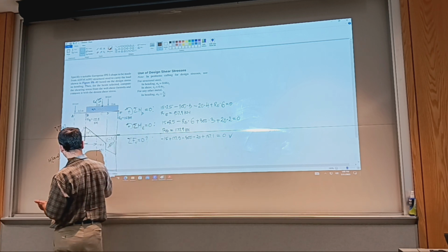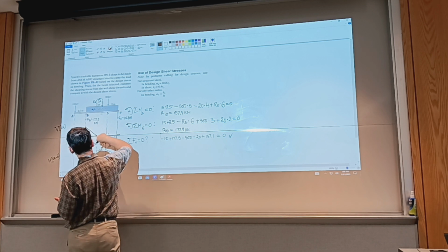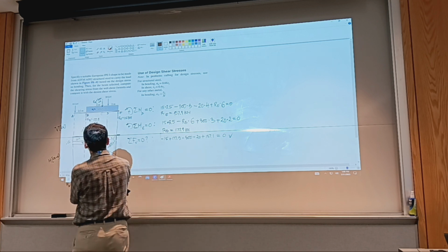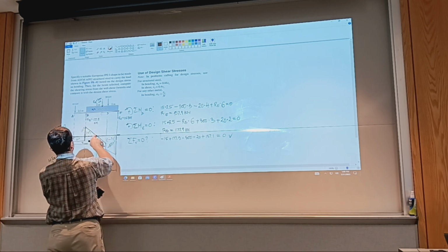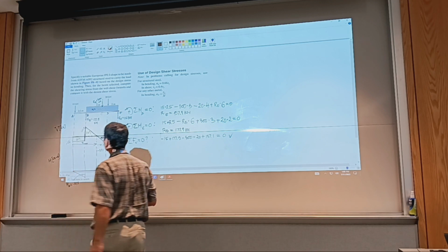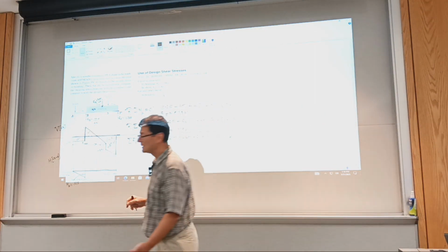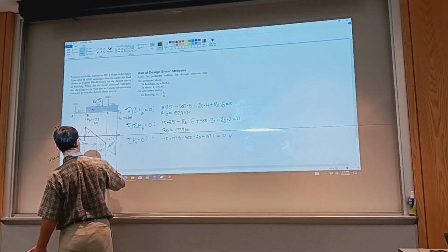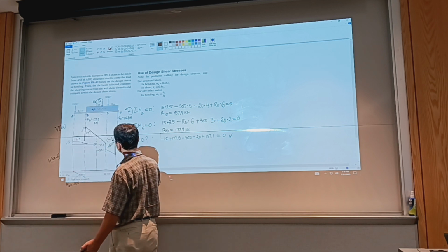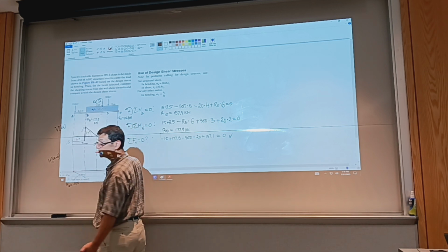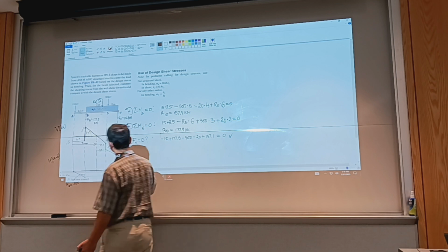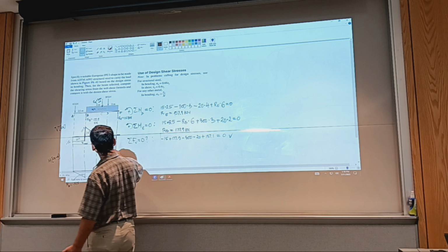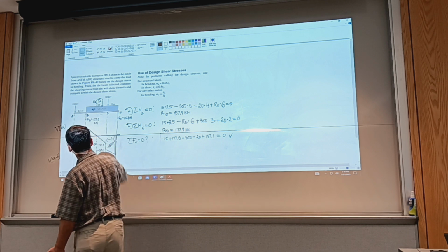I have this value, 37.5, and to it I'm going to add, well, can I calculate this? So I have a triangle. I need to find x, m max at this point, because I need to know what this positive area is and what this negative area is to find m. The other option is to evaluate this area. I could do that too, going from right to left, and take it as a positive because I'm going right to left. So we can do that and then verify after finding what x max is.